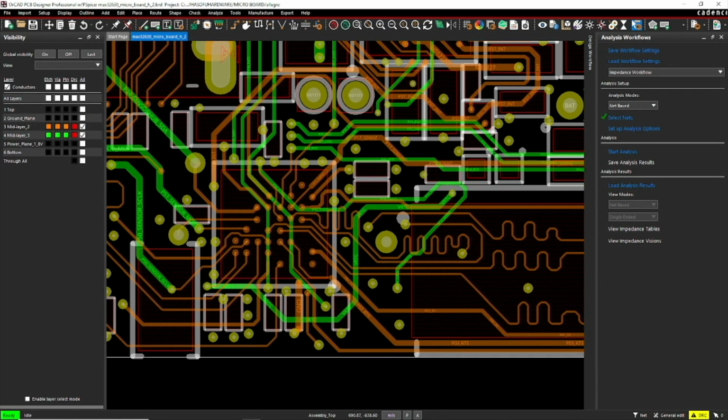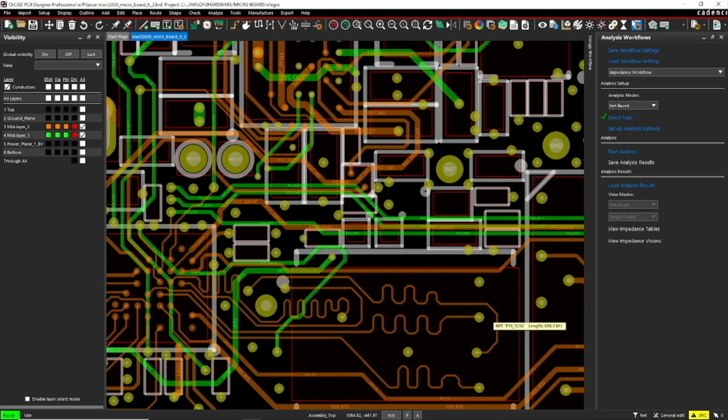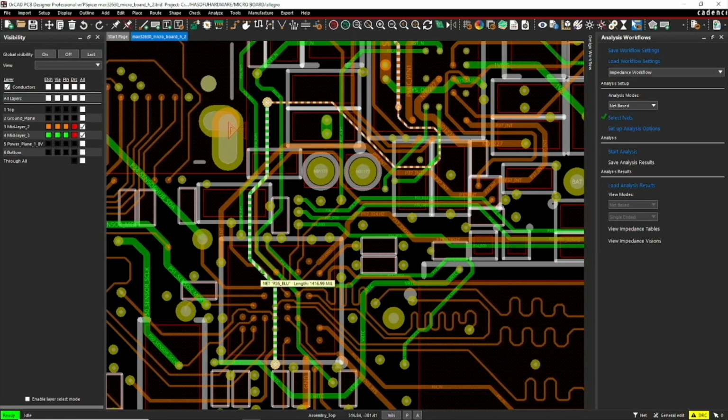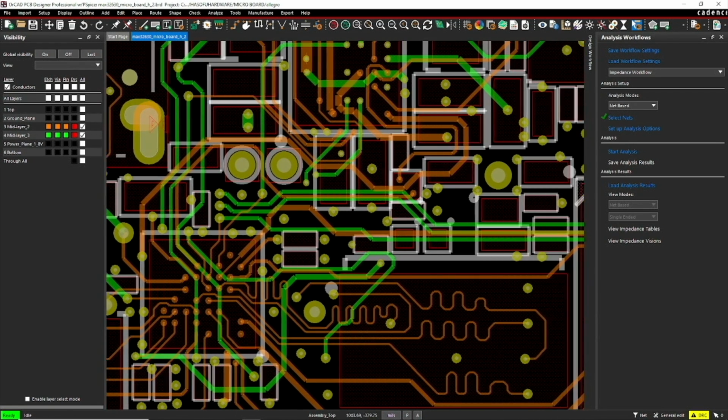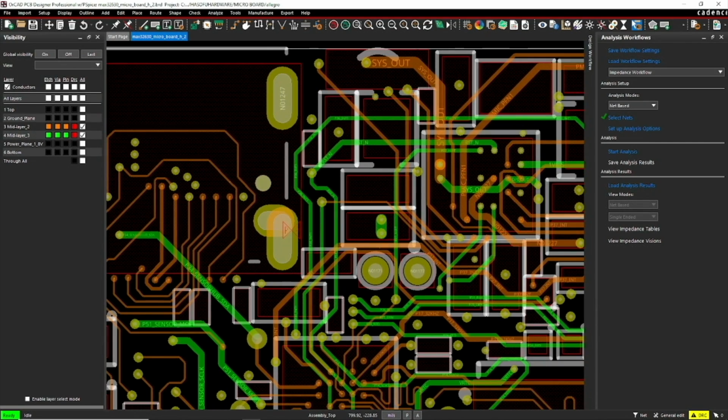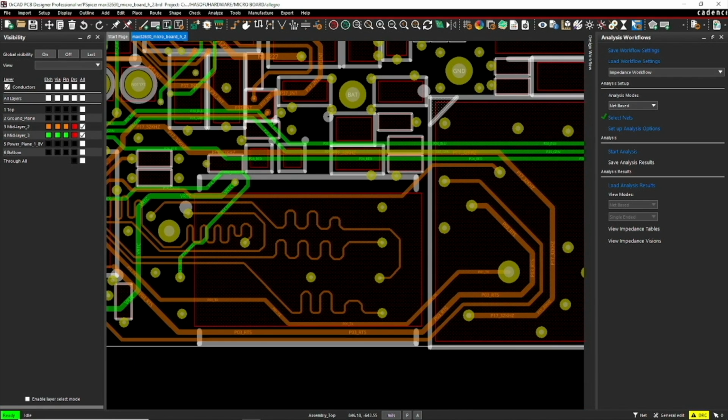It would be a problem if you create opportunities for sensitive traces to couple their EM waves with each other. But we can avoid that by moving traces away from each other or routing them orthogonally to one another if they are on adjacent layers. And the engineers have done that here. For most of these traces, they are routed somewhat orthogonally to one another, and areas that have high-speed traces are kept far away from other traces. This method is not as ideal as a whole reference plane shielding these two layers, but these techniques are still